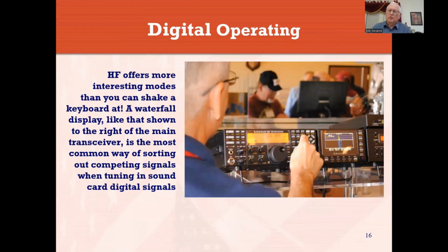There's a picture on the right side there that shows a waterfall with just a single display in it. As you can see, going from top to bottom there, you've got the blue, which indicates the signal. There's not a lot of strong lines on either side of it, indicating that the sender was not overmodulating. So that looks like a good solid signal.